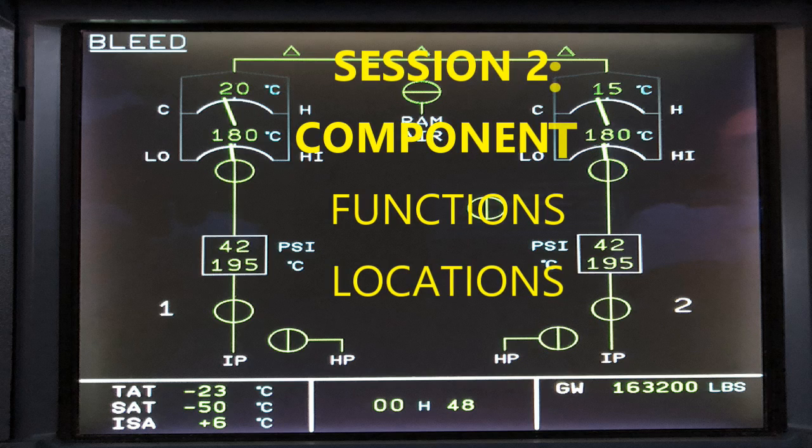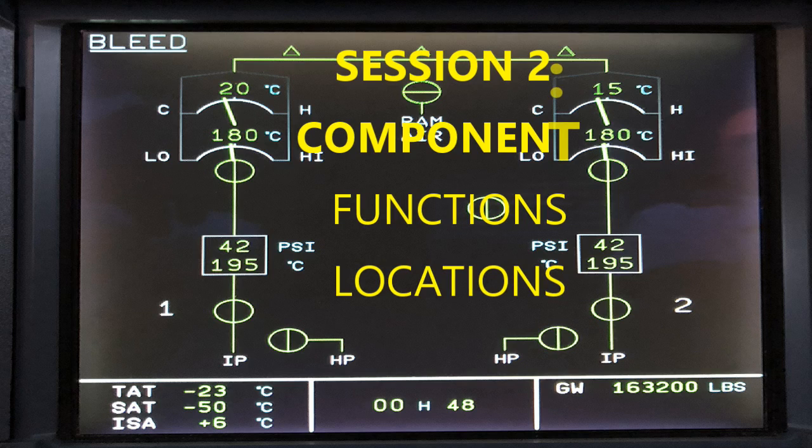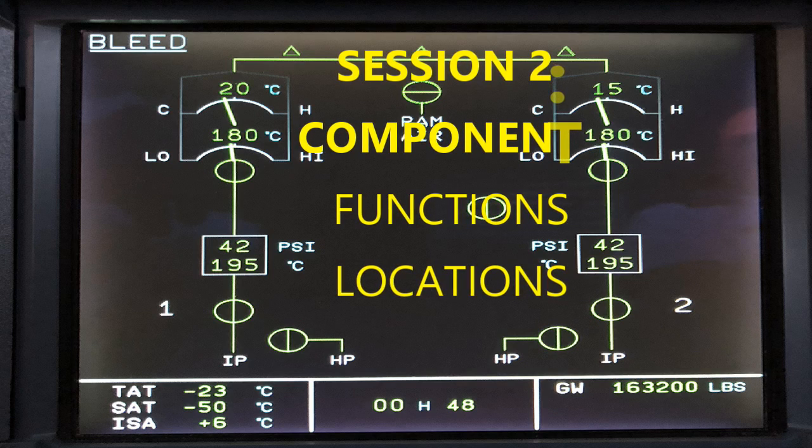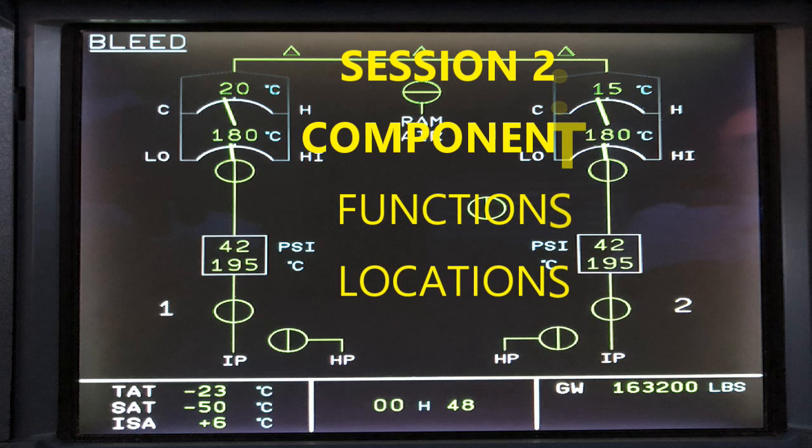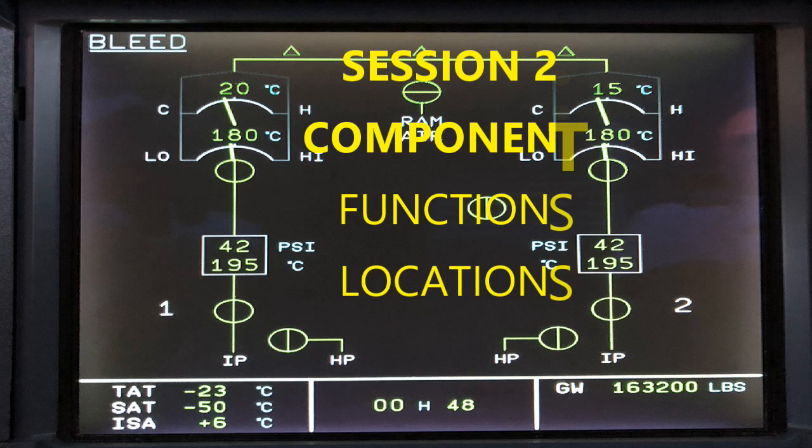And of course you can see the positions of the different parts of the load valve. With your pneumatic actuator, you've got your electrical receptacle, a visual position indicator, you also have the position indicator switch, and a test port. And of course your butterfly in there, so you've got all that.